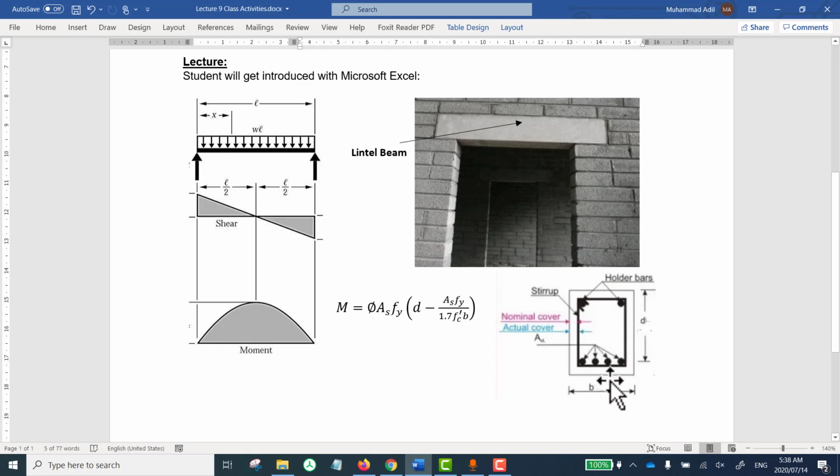And the width of this beam in the cross section is b, which you can see here as well. And you can see that the maximum bending moment is produced in the middle. Let's call that M, and that bending moment from this load W, or W load distributed on top, will be W L squared over 8.